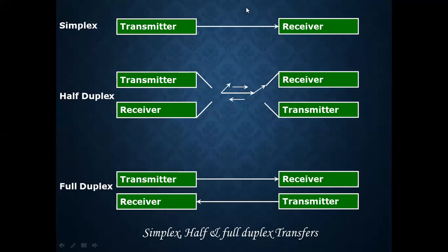So you cannot reply to the radio. You are only listening. So from the radio station to your radio receiver, only one-way communication is going on. This is the example of simplex communication. Okay, now what is half duplex? Now half duplex is, have any of you used a walkie-talkie or something?